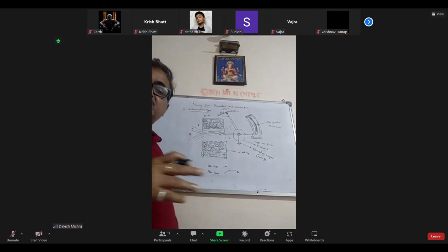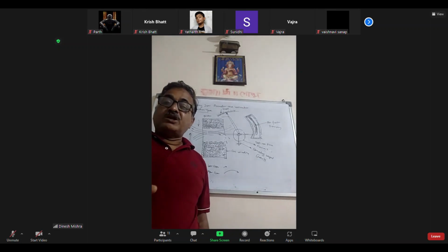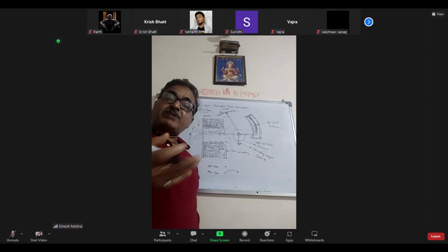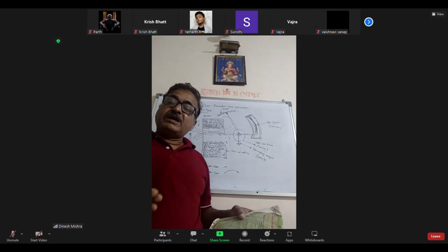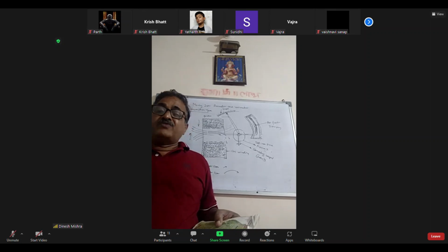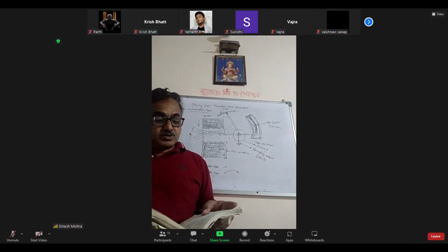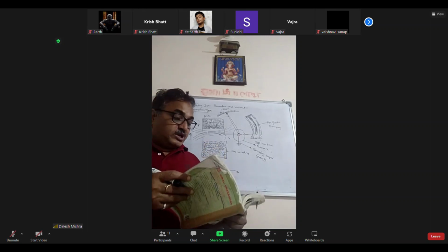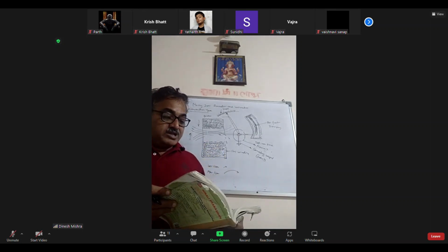The deflection of the pointer depends upon the strength of the current, that is, the strength of the magnetic field. Okay, if the current is less, the magnetic field strength is less, deflection is less. If the current is more, magnetic field strength is more, deflection is more. Is that right? Okay. So the controlling and balancing weight are also shown. It gives the controlling torque.